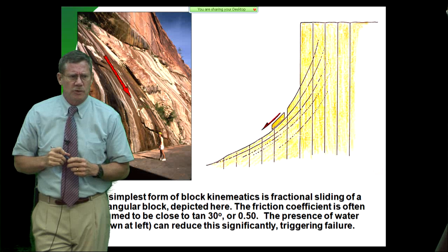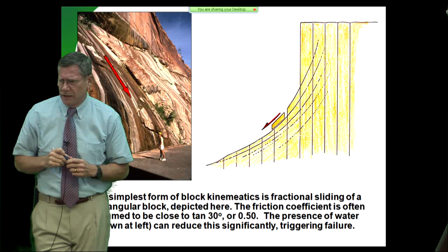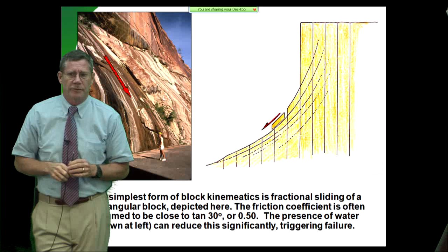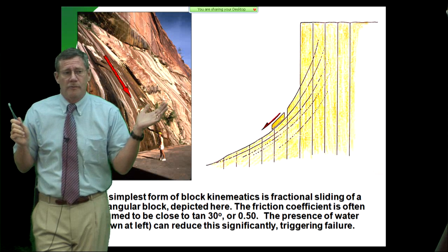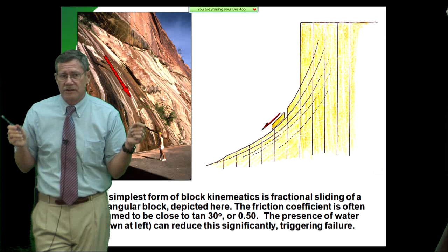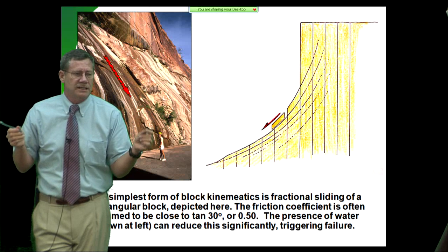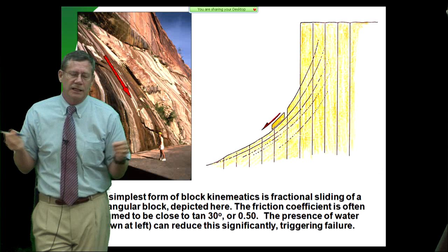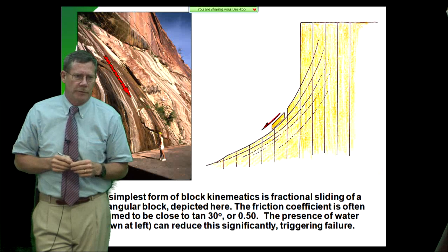But a drain is a hell of a lot better than no drain. And if you get enough pore pressure on it, it's going to relieve the pore pressure. You're not trying to drain the whole mountain and start a water company. You're trying to alleviate excess pore pressures. It's not about volume. It's about alleviating trapped pore pressures.